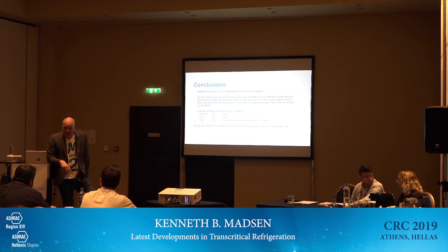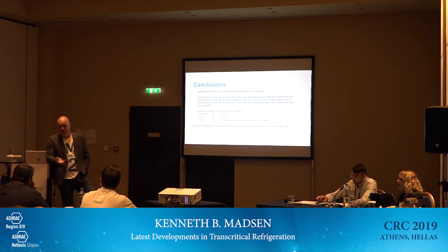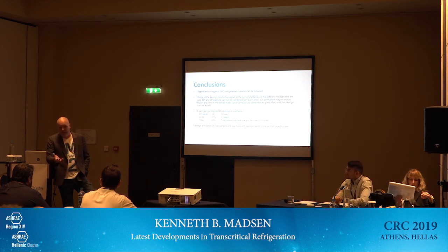And if there's something on the rack telling that we are not able to remove the liquid, then they send a signal to the controller to switch back to a second set point where they have a higher superheat and where they also have all the safety functions. So that's the Danfoss way of doing it. But Copeland and the others have something similar. I'm not that much into details.